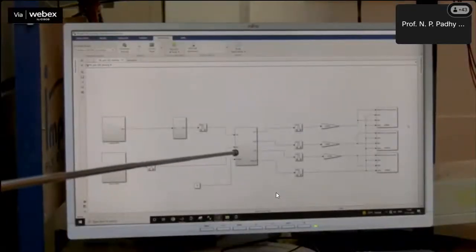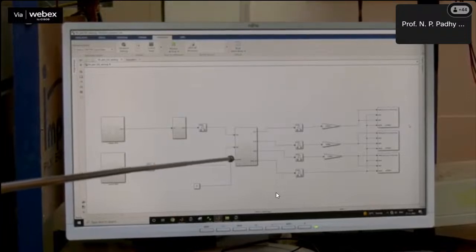Initially, the grid-tied DC microgrid is simulated in Simulink and the corresponding control is implemented in the same Simulink. Make sure that this simulation runs perfectly. After simulation, remove the plant and keep the control system that is required in the DSP.